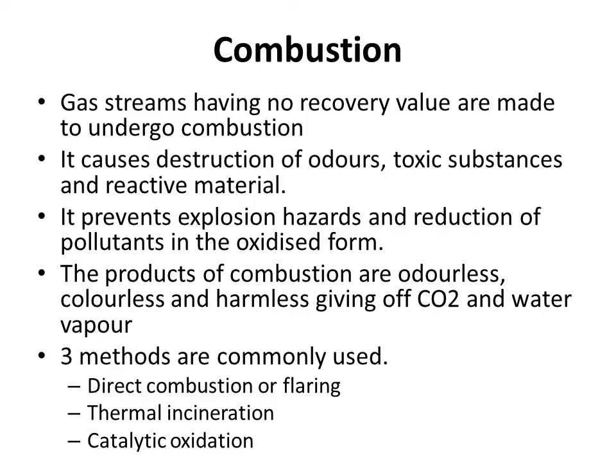When the pollutant is destroyed, the combustion must be complete. Otherwise, intermediate products of combustion will form, which may be more noxious than the original contaminant. The common methods that are used in combustion are direct combustion or flaring, thermal incineration, and catalytic oxidation.